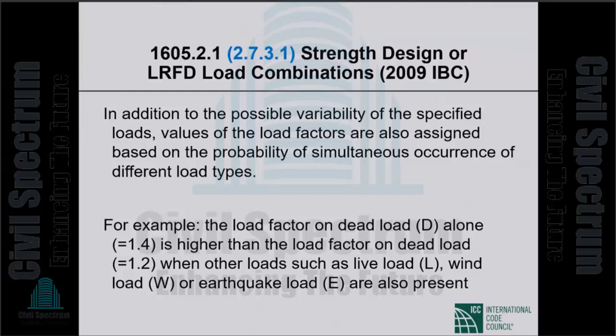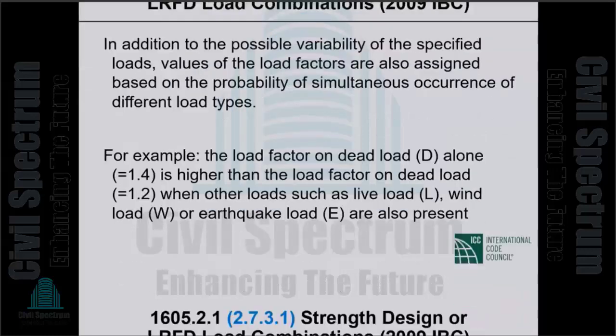Yeah, so in addition to the possible variability of the specified loads, values of load factors are also assigned based on the probability of simultaneous occurrence of different load types. For example, the load factor on dead load alone, which is 1.4, is higher than the load factor on dead load, 1.2, when other loads such as live load, wind, etc. are also present.